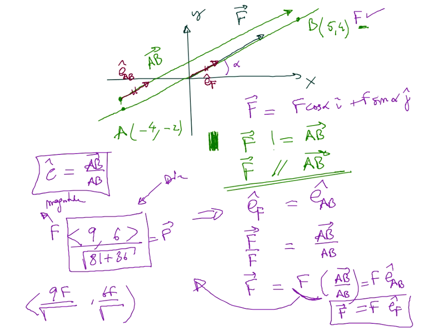Okay? So the big thing is, as you realize that the force that you're looking for is parallel and in the same direction as a position vector, then you want to express that vector in unit vector notation, which allows you to separate the magnitude from the direction. You should be able to express the direction easily from the property of the position vector along which your force is aligned.